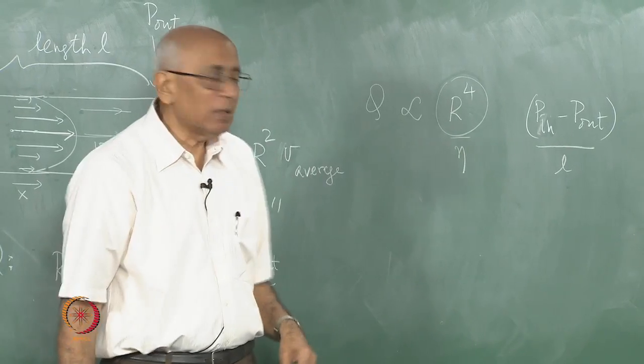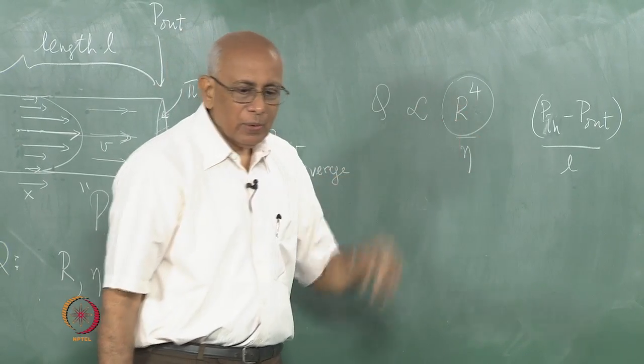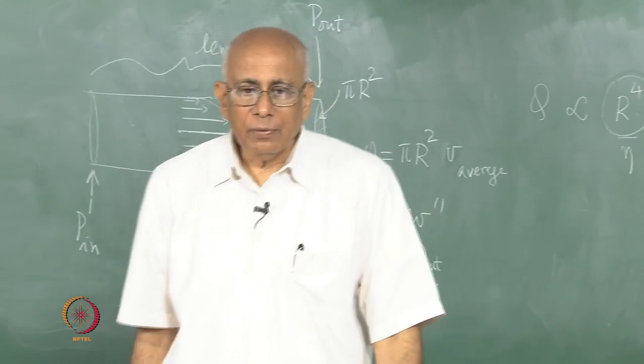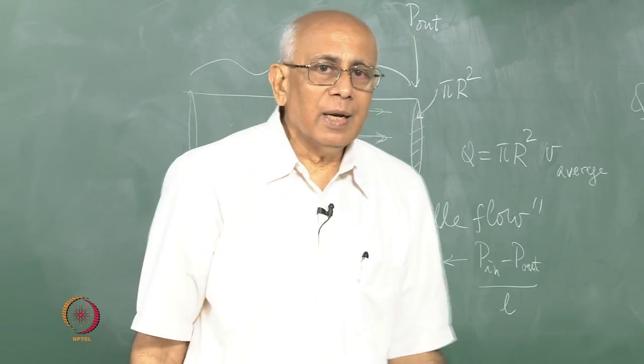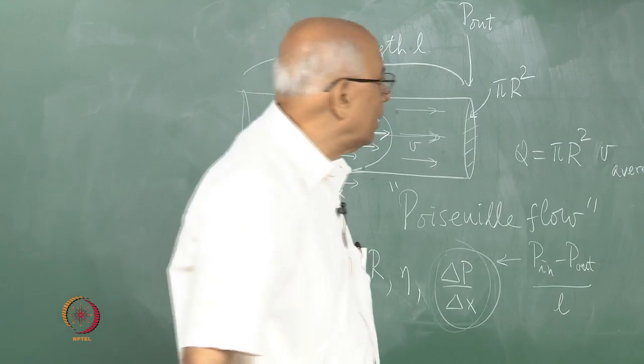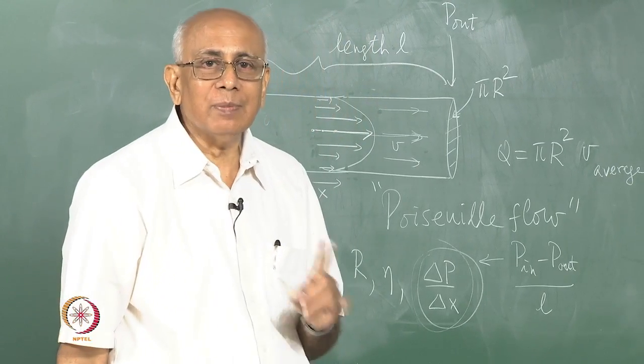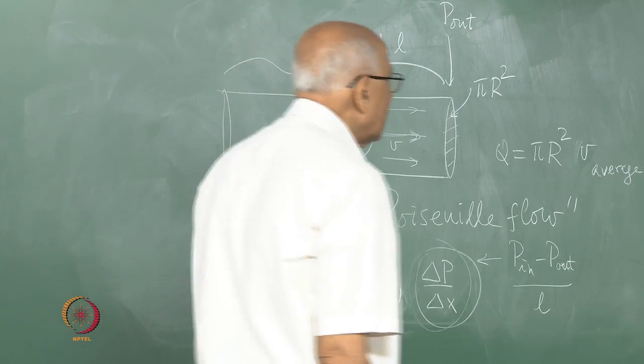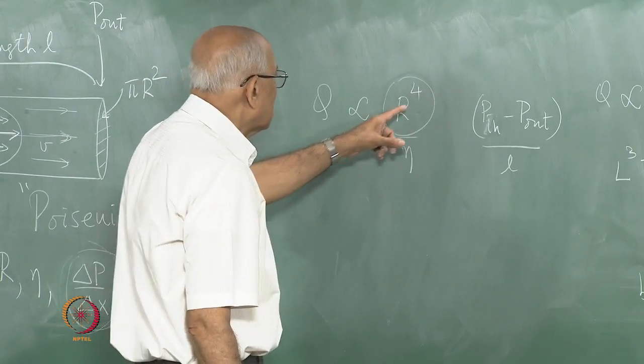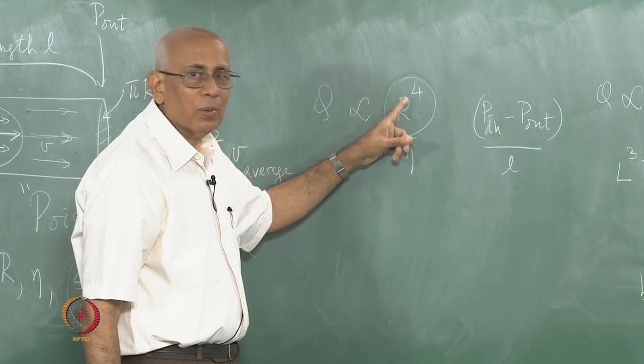And it is quite a surprising formula that there is a 4th power here. So it really says that if somebody quietly doubles the inlet pipe radius, then he or she gets actually 16 times as much water. The discharge rate increases drastically. So this is therefore a very, very sensitive quantity here.